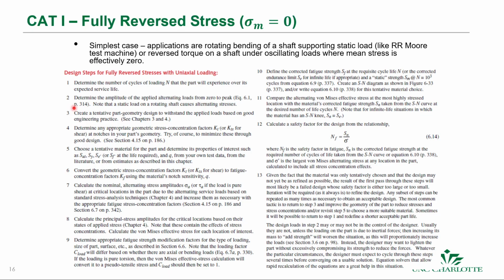So there's this native chicken and egg problem for so many of our design problems. And it's really why I'm pushing EES, because it's a nonlinear system of equation solver. So you can put all your equations in there, put all this information, and then play around with the variables. And all of the other variables are automatically accounted for, and it's easy to solve.